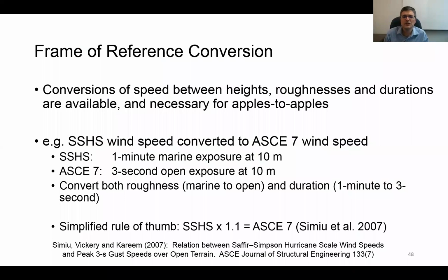Right. So I think I already touched on this, the frame of reference conversion. We have height as a frame of reference, we have roughness as a frame of reference, and we have duration as a frame of reference. If you want to convert from one to the others to do an apples to apples comparison to, for example, extrapolate what you measure at one location to a different location with a different exposure, there are ways of doing conversions. In other words, if I'd only measured what I measured in the open field in the previous slide and didn't measure behind the suburb, there are ways I could extrapolate and get a decent idea of what I would have measured behind the suburb by using conversions.